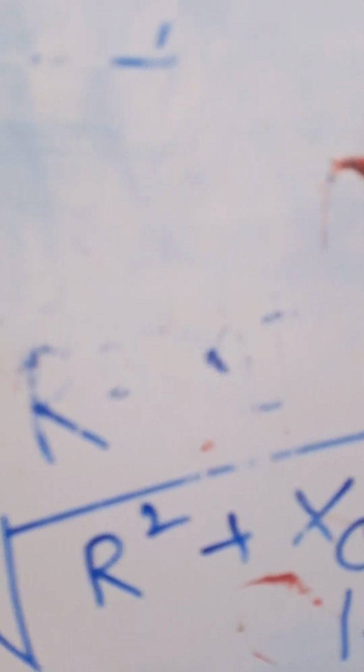Next, viva questions. What is the DC generator and motor? Why are armature cores laminated instead of solid core? To reduce the eddy current losses. How can you minimize the hysteresis and eddy current losses?